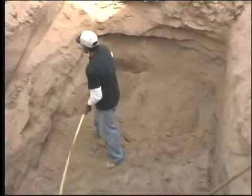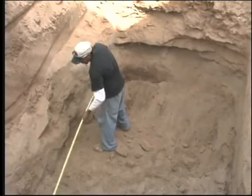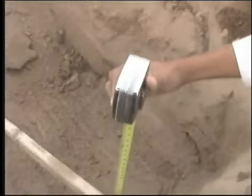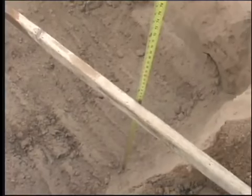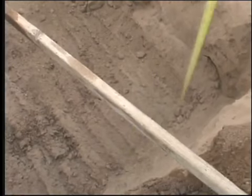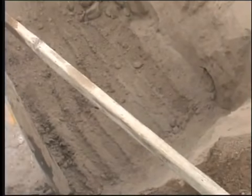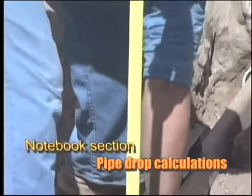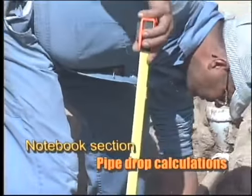When you dig, the hole should be approximately 2 feet larger on each side than the septic tank being placed into the hole. This measurement is from the bottom of the hole, not the top, since the sides of the hole are seldom straight up and down. The depth of the hole for the septic tank is usually determined by the drop in the pipe required for the water to flow from the house to the septic tank. Calculation details are given in the notebook section entitled Pipe Drop Calculations.